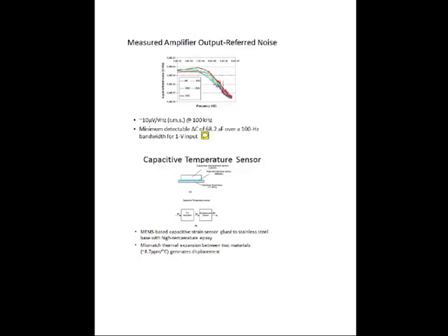So it gives us about 68 dB dynamic range. But this calculation only takes into account the amplifier noise. This ignores the sensor noise, which, I mean, the sensor will have resistor, and this is a very good optimistic result.